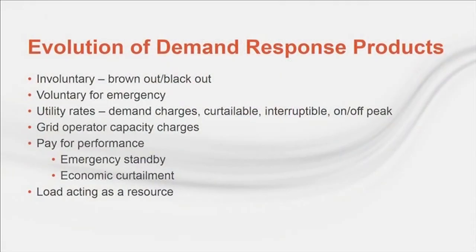No, it's not. Demand response has been with us in some form or other since Edison opened the Pearl Street Station in the 1880s. Over time, utility metering and communications developed and customers became more aware. Control technology evolved, eventually to the point where utilities and grid operators developed a variety of formal policies and programs to take advantage of the customer's ability to control how much energy they used, and more importantly, when they used it. We started out with basically involuntary blackouts, and have progressed enough that load is now considered a resource on par with actual physical generation. This opens up a whole new world of opportunities for progressive thinking energy users.